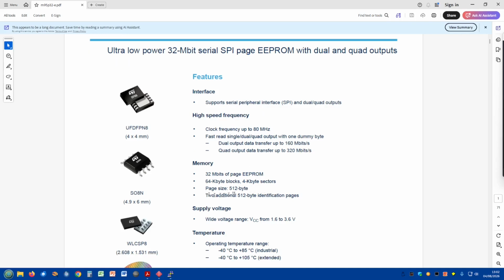It's got this page size of 512 bytes. So that's basically like your sector on a disk drive. We could ignore all the other ways that it does things. We will just be looking at these pages. I'll refer to them as pages all the time because they are like sectors, but the documentation says pages all the time, and then a sector on this IC is 4K. So it could get confusing, so we just call it pages. This is the smallest size chunk of data we can access on this IC in one easy hit.